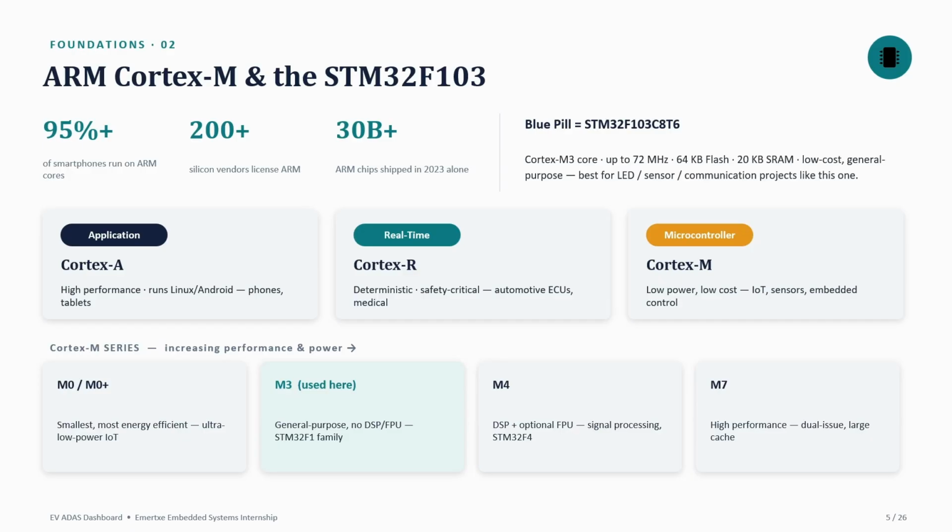It runs at up to 72 megahertz with 64 kilobytes of flash memory and 20 kilobytes of SRAM, which is low cost and essential for running our simulation projects.